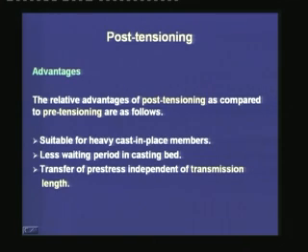In my earlier lecture, I had mentioned that the pre-tensioning operation is suitable when the members are produced in bulk, like electric poles and railway sleepers, and when those members are relatively lighter than the bridge decks, which are usually post-tensioned.